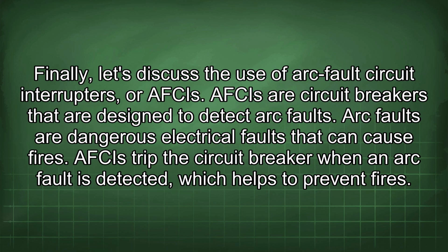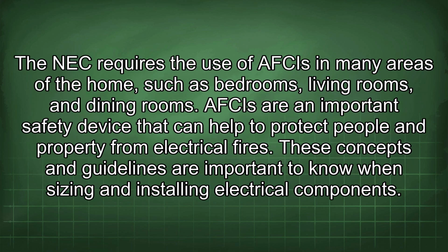Finally, let's discuss the use of arc fault circuit interrupters, or AFCIs. AFCIs are circuit breakers that are designed to detect arc faults. Arc faults are dangerous electrical faults that can cause fires. AFCIs trip the circuit breaker when an arc fault is detected, which helps to prevent fires. The NEC requires the use of AFCIs in many areas of the home, such as bedrooms, living rooms, and dining rooms. AFCIs are an important safety device that can help to protect people and property from electrical fires.